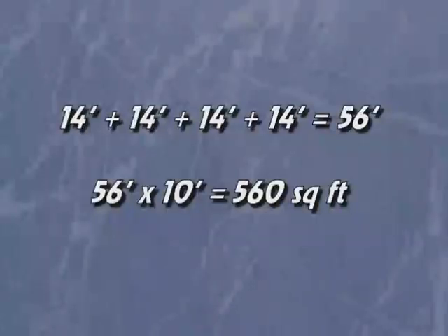Now, to get the square footage, we need a height. We would think frequently, well, it's 8 foot, just like most places. But look down in the right-hand corner of the plans. 10-foot ceilings throughout. So this is unusually high for the typical building. So we need to figure 56-foot length times a 10-foot height. And that will give us 560 feet, or square feet.